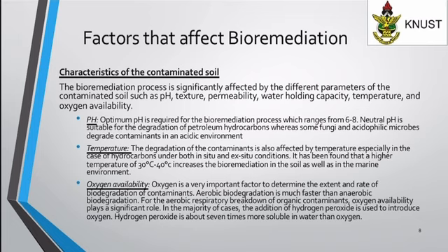For the aerobic respiratory breakdown of organic contaminants, oxygen availability plays a significant role. In the majority of cases, the addition of hydrogen peroxide is used to introduce oxygen. Hydrogen peroxide is about 7 times more soluble in water than oxygen.